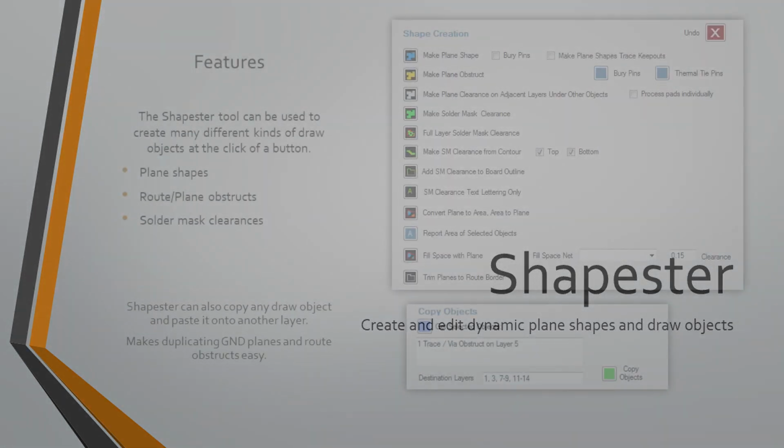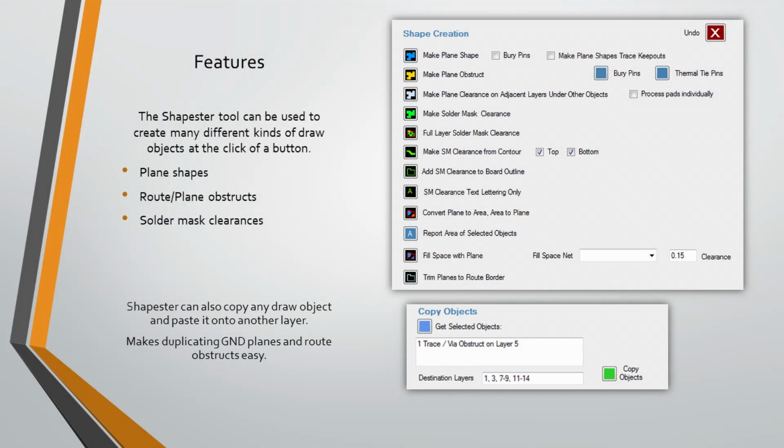The basic idea of Shapester is to create shapes based on other design objects. For example, in a power supply circuit, a group of pads from a regulator chip, some capacitors, and an inductor can be used to create a plane shape which encompasses them and joins them together. This is very useful in boards where there are many power supplies creating and delivering power to distributed devices.